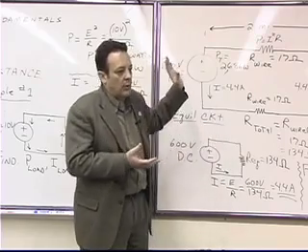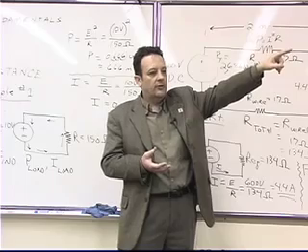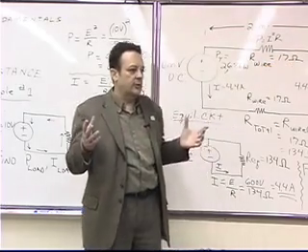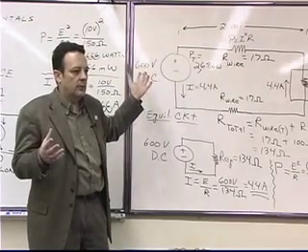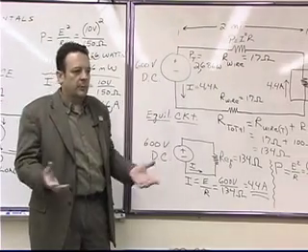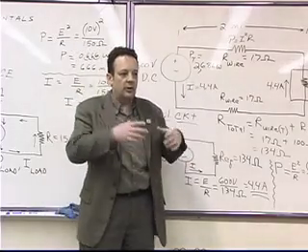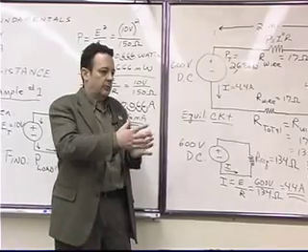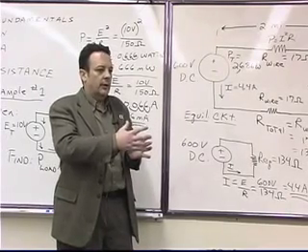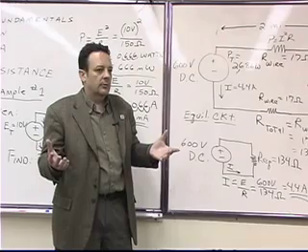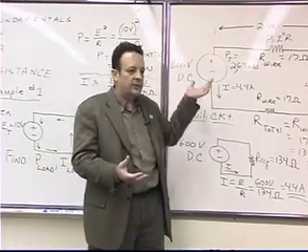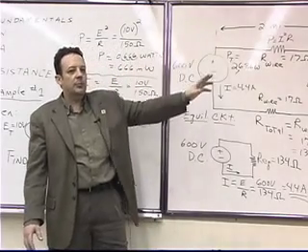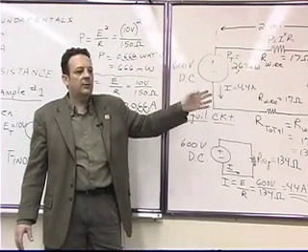But to use it to drive a water pump that's 2 miles down your property is going to be a highly inefficient utilization of that energy. You might want to build a swimming pool or put in a jacuzzi or something else that would require energy that would be closer to your solar panels and thus more efficient. This way, you're wasting over 1/3 of your energy in just getting it to the pump. Why do you want to do that?